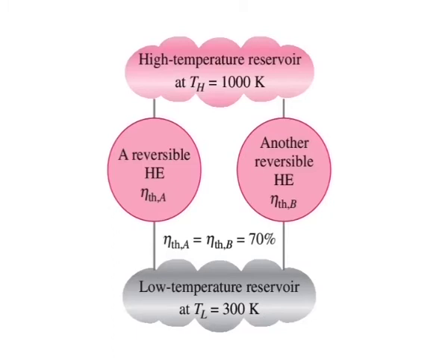This time, let us replace the irreversible engine by another reversible engine that is more efficient and thus delivers more work than the first reversible engine. By following through the same reasoning, we end up having an engine that produces a net amount of work while exchanging heat with a single reservoir, which is a violation of the second law.